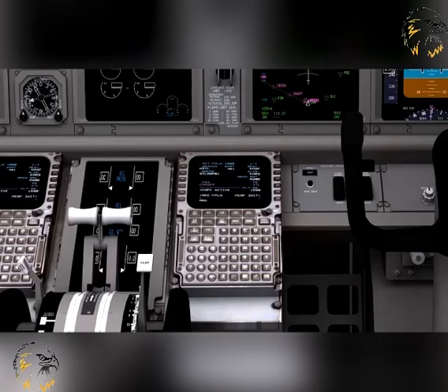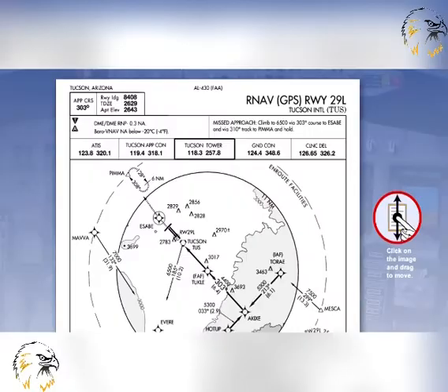FMS or RNAV equipment may also be used when flying defined departure procedures, providing the procedure is monitored using the basic display normally used with that procedure, and the tolerances for flight using raw data on the display are complied with. GNSS procedures allow for SIDs to be downloaded into their databases and a fully automated departure completed. As in the case of the FMS or RNAV procedure, the pilot is required to monitor the procedure with reference to the direct input data from other nav aids, such as VOR, NDB, or DME.